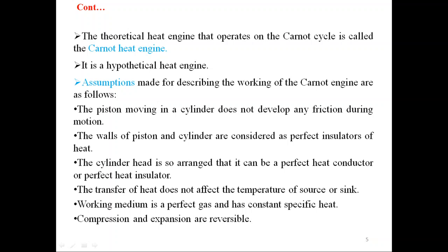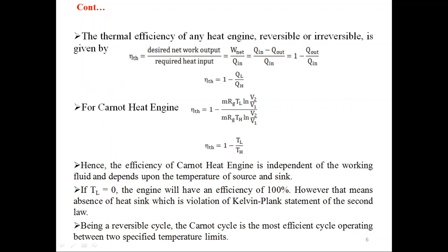The walls of piston and cylinder are considered as perfect insulators of heat. The cylinder head is so arranged that it can be a perfect conductor in case of isothermal process, or a perfect heat insulator in case of isentropic process. The transfer of heat does not affect the temperature of source or sink, that is TH and TL. Working medium is a perfect gas and has constant specific heat. Compression and expansion are reversible.